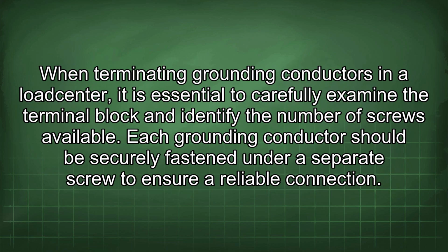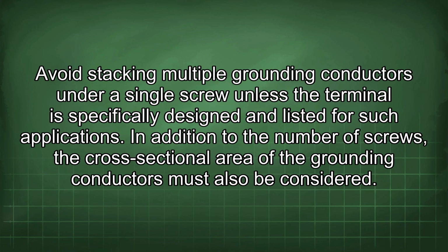When terminating grounding conductors in a load center, it is essential to carefully examine the terminal block and identify the number of screws available. Each grounding conductor should be securely fastened under a separate screw to ensure a reliable connection. Avoid stacking multiple grounding conductors under a single screw unless the terminal is specifically designed and listed for such applications.